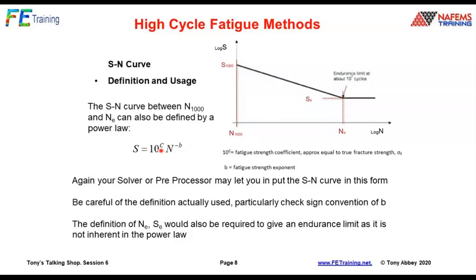We've got a coefficient, which is the fatigue strength coefficient. That's some fundamental data you've got to test for. You're going to be fitting through lots of data to try and find that. And then the slope of the curve, the strength exponent, again, you're going to be testing for that. So you hope to get values for C and B. If not, you can use the 0.9, 0.5 trick. Watch out to see what your preprocessor is going to tell you you're doing there. But that's basically our rule, what we base everything on.